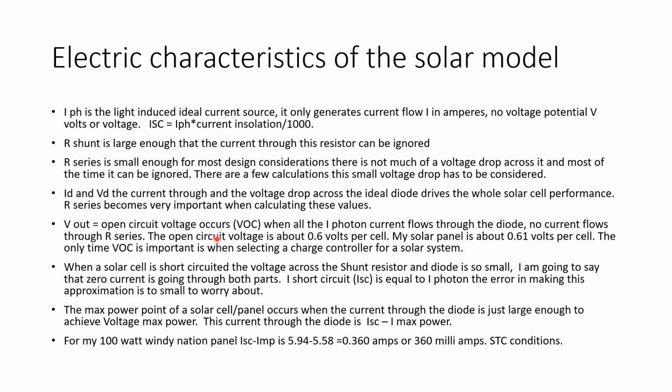In designing circuits, we usually put a derating on electronic components of about 70%. For capacitors, we usually put a 50% derating on the capacitor. So if we want a 50 volt capacitor, we use a 100 volt capacitor.